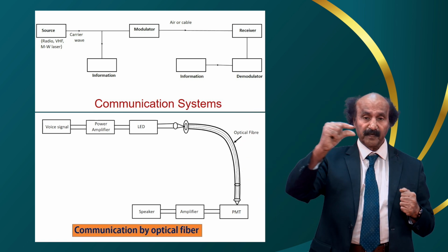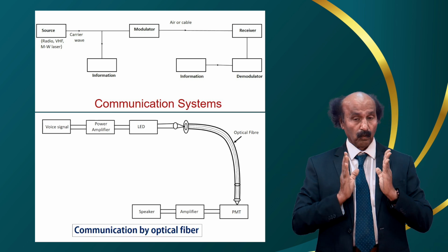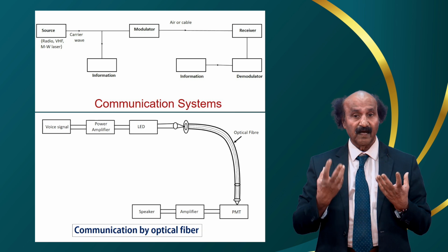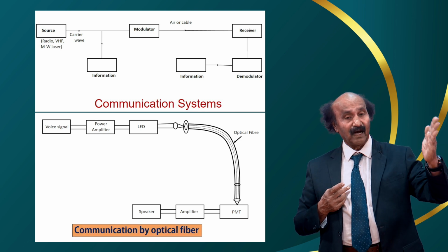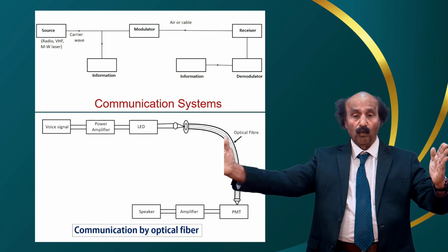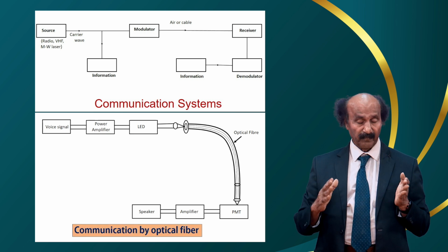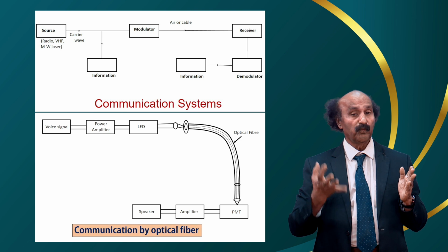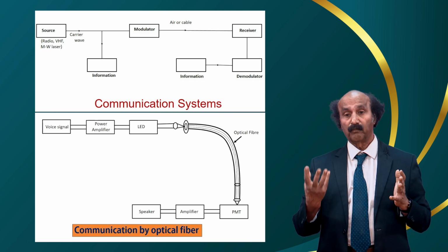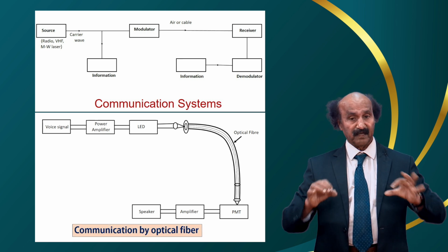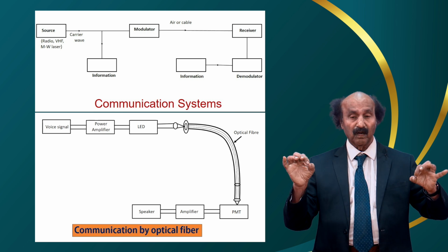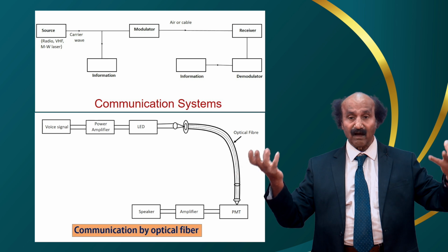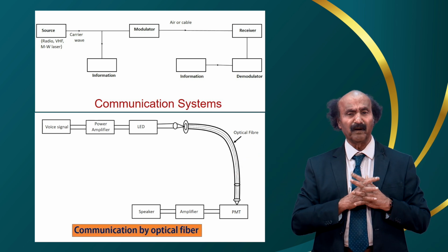If the optical fiber is really good in quality without any kind of inhomogeneities, then if we have sent 100 photons this side over a distance of 1 kilometer, you may get almost 90 photons. You will lose only about 10 photons, provided the optical fiber is pure, without any other flaws, cracks or anything. These are all specially prepared materials.